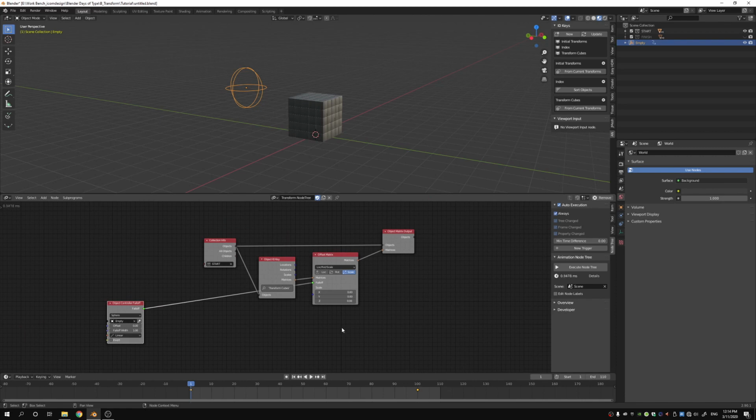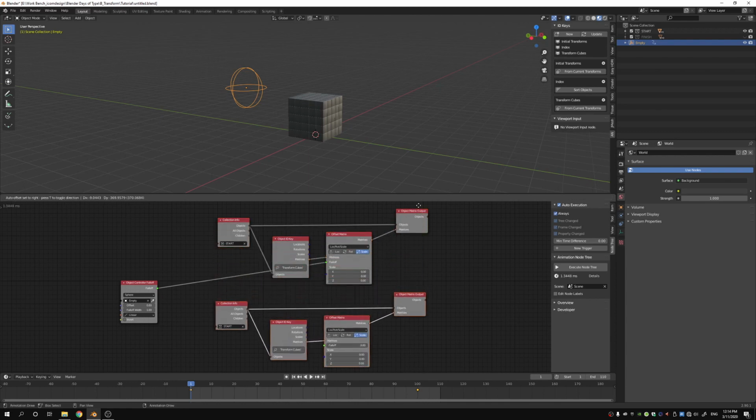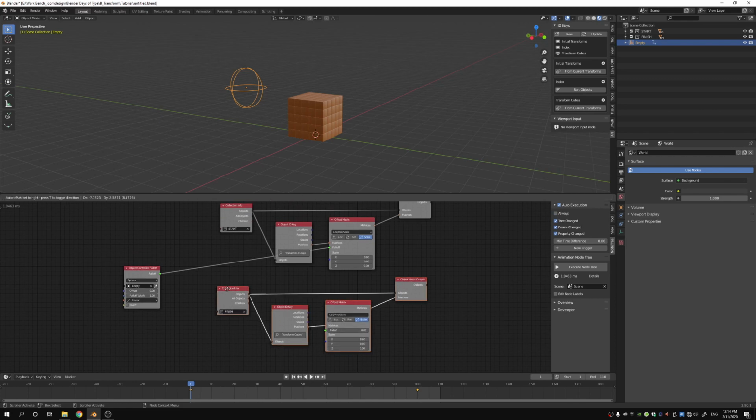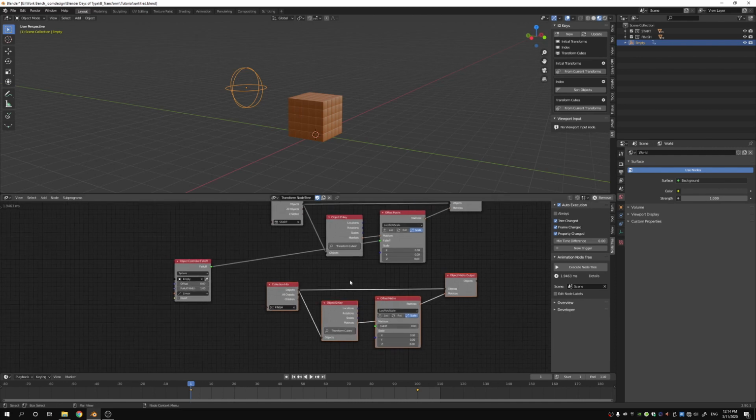What we want now is to duplicate these nodes, Shift D, and associate these nodes with the finish collection. So we'll turn that on. In this case, instead of start, we'll choose, that's why we need always off, because it won't allow me to select that. Select finish. Now we have a similar setup for the orange cubes.